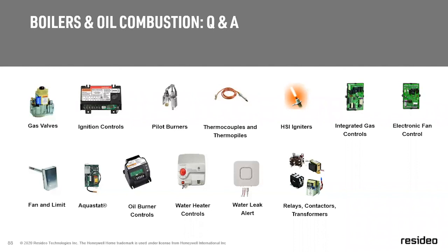We also can wire that up to the thermostat with a dry contact on the Prestige IQ, and you'll get a notification on the thermostat itself. Or if I have remote phone access, I would get an alert. Let's say I had a church with a couple boilers and one of the boilers dropped out on safety, I'd get an alert to roll a truck to that location.